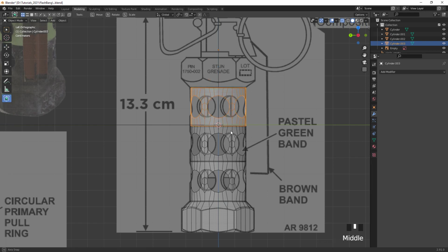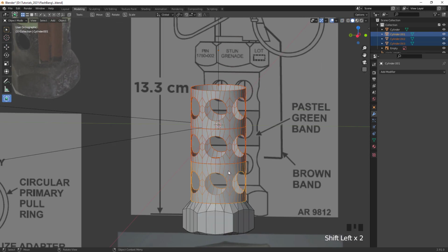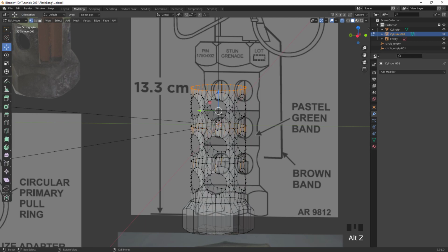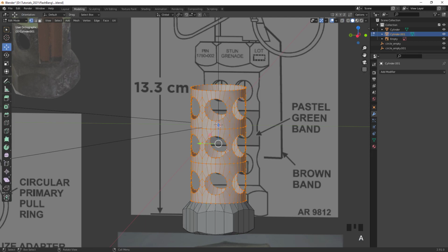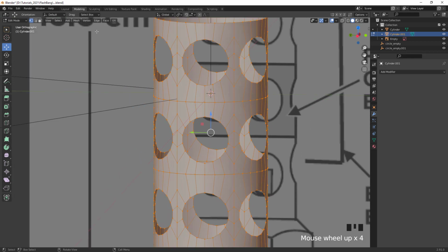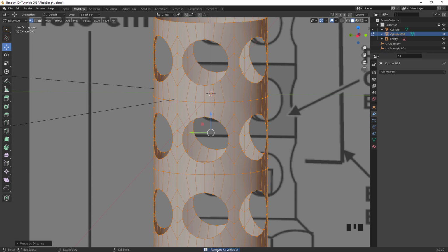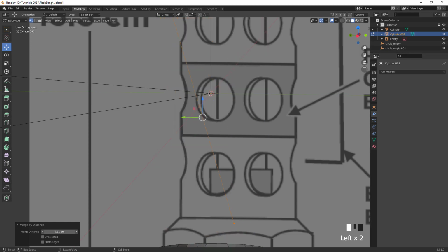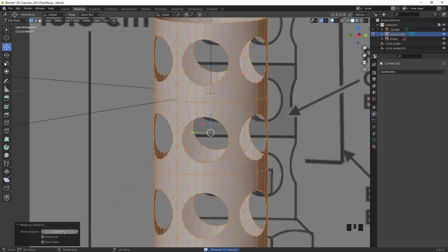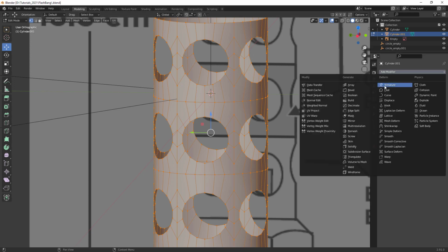And now what we do is with Shift, we make a selection and then we press Ctrl J to join it. So now I'm gonna go over to vertex mode, select everything here while we are in our edit mode again. And then under Mesh, you can go over here to merge by distance, and you can see how that welded everything together. And we can also change the threshold if you're getting any issues there. So make sure it's a low enough threshold, but that you also see that it actually welded something.